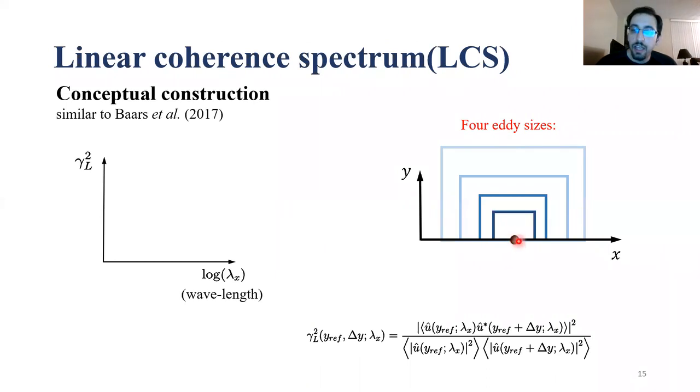Suppose we have a hot wire, which is the reference hot wire and located at y = 0. And we have another hot wire that is within the flow field of the largest eddy. So at this position, both the fixed hot wire and the traversing hot wire, which we are going to traverse closer later on, are measuring the flow field created by the largest eddy, and the length of this eddy is L1. Proportional to this length, L1, is a wavelength, lambda 1.